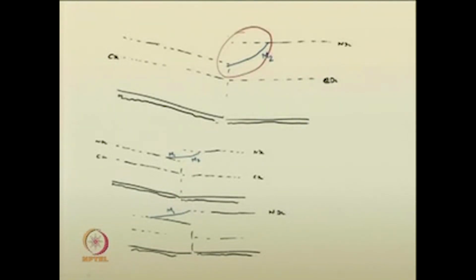Here, in this situation, the M2 curve in channel 2 has a positive slope, the water surface slope is positive here. So, theoretically not possible, because dy by dx is positive there. So, this portion does not exist, such a water surface profile will not exist.